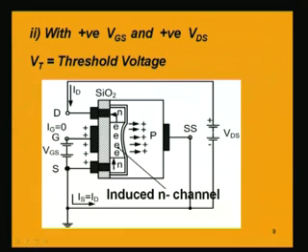If you recall, in a P type semiconductor the holes are the majority carriers, and here if we are pushing away the holes, they will be uncovering the immobile charges, which are nothing but the acceptor ions, which are negative ions.